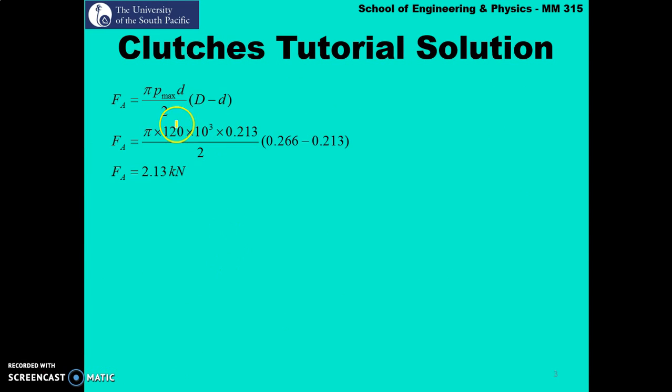Now the next thing is we have to find the actuating force. So you need to understand that whenever we are calculating actuating force, it is independent of the number of frictional surfaces that are given to us. So actuating force again for uniform wear is given as pi p max small d, which is inner diameter, divided by 2, multiplied to outer diameter minus the inner diameter. So substituting for your outer and inner diameter, we obtain our actuating force of 2.13 kilonewton.